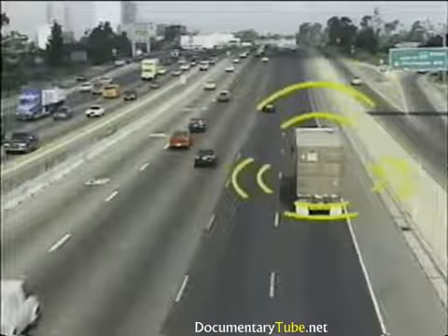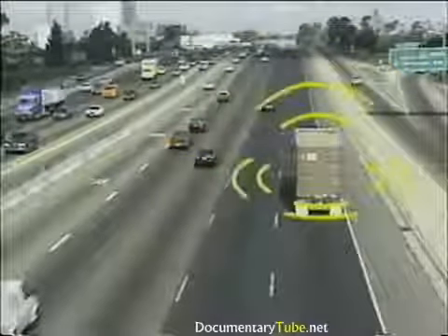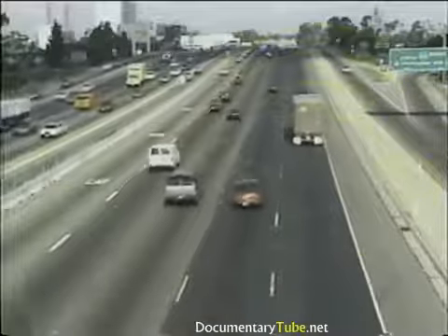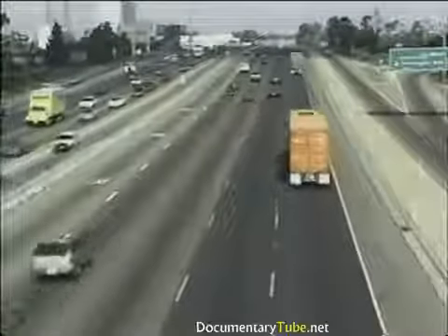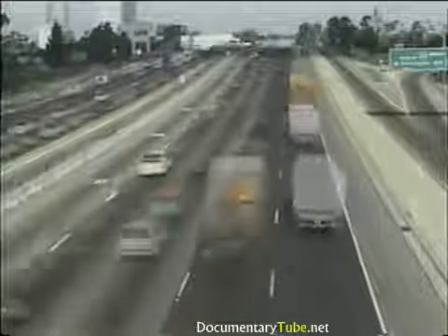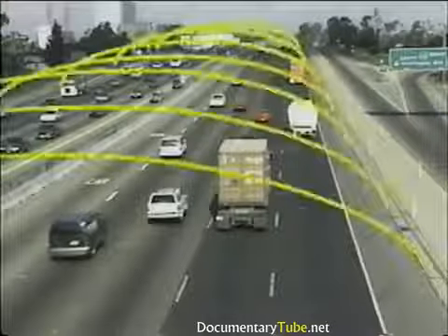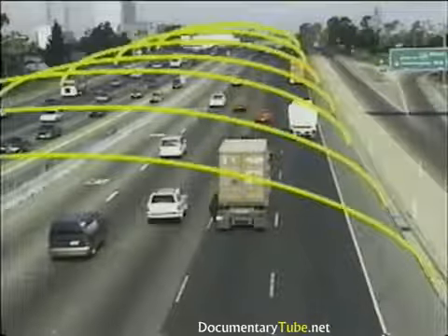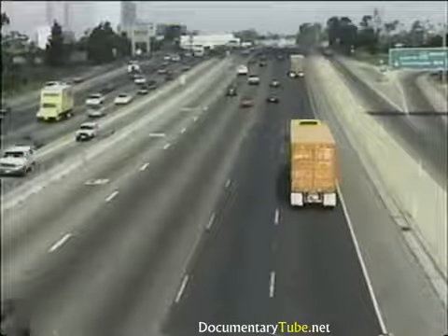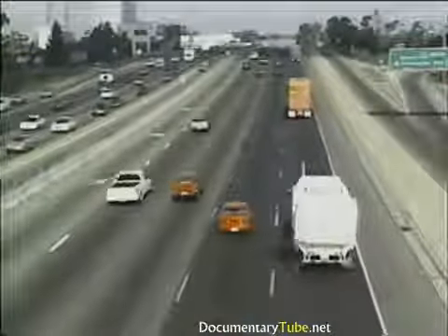Whereas individual vehicles are here considered as point sources, highway traffic can be considered a line source. It is composed of several vehicles or point sources closely spaced. A community is a sufficient distance from the highway to see highway traffic as a line noise source. This implies that for highway traffic noise, the sound decreases due to cylindrical spreading at a rate of 3 dB per doubling of distance away from the road.